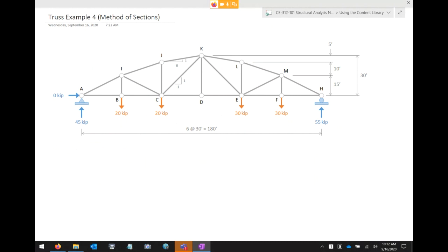Right. If there was an X component for the reaction force at A, would it be more judicious to choose the right side for analysis? That's a good question, and if we're being strict about it, there might be an argument to be made to cut a section and look to the right, because you've got two loads and a reaction to the left, two loads and a reaction to the right. That might be what swings your vote.